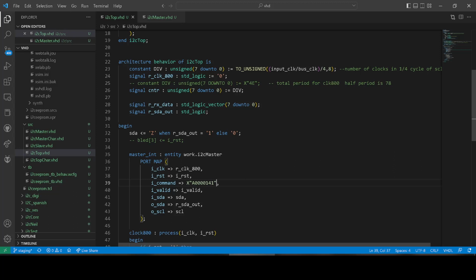I2C serial bus. And so, like I said, when the output data is at a high condition, make my serial data a high impedance, therefore allowing whatever input comes in from the slave to show up on the bus. Otherwise, we'll just send over our 0.